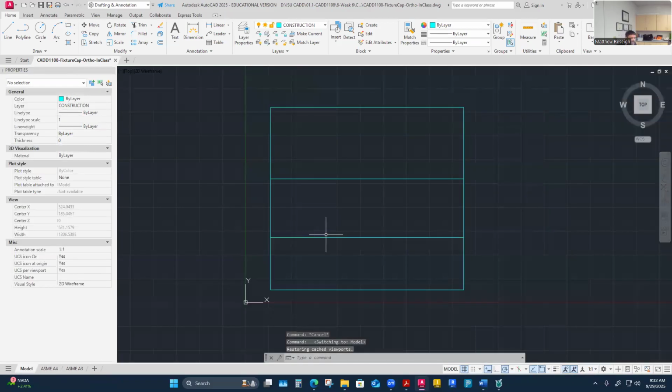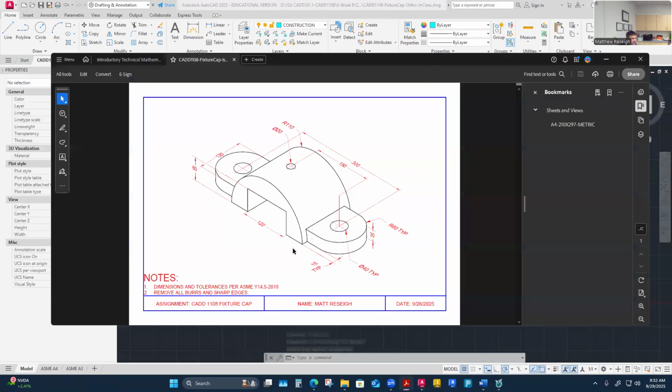Yep, totally. Now I'm going to start detailing this here. So I think we could start with front or top. I don't think it matters too much other than that I've got kind of a circular feature, but I'm going to assume that the center of that is perfectly cut off here. So this is going to be just a radius 110. And then I've got the inner slots, which are 60 by 120, cut through there. Then I'll see these ears that come out, they're 30 millimeters high.